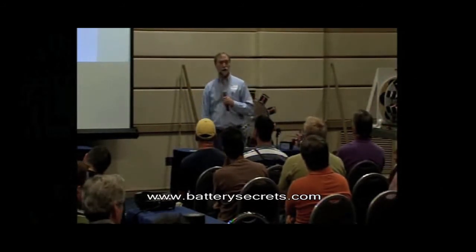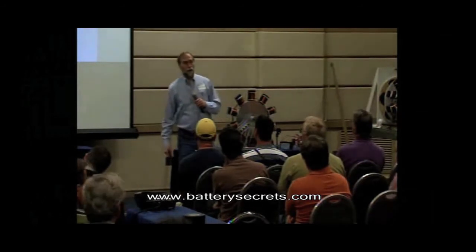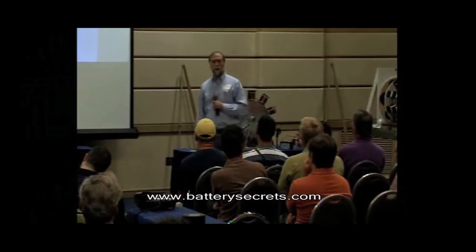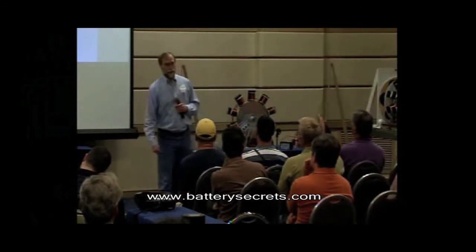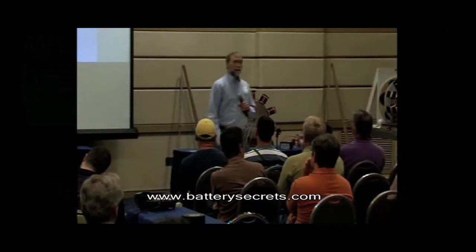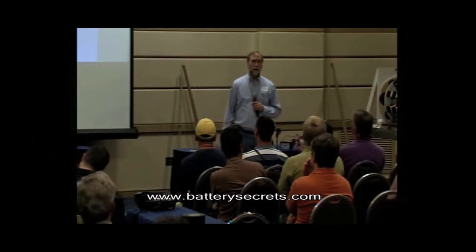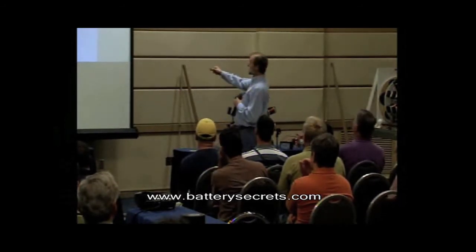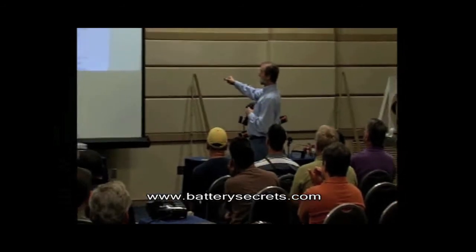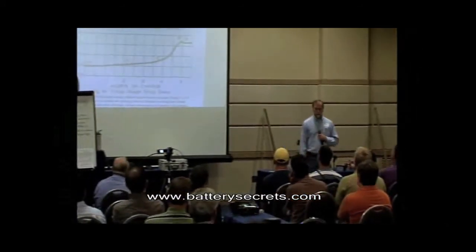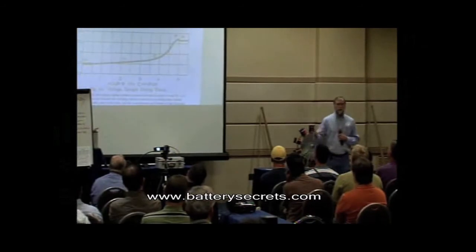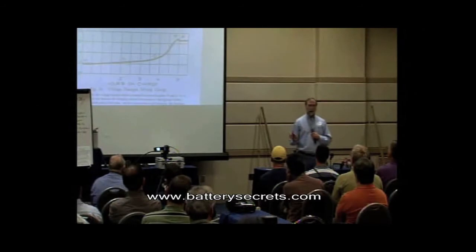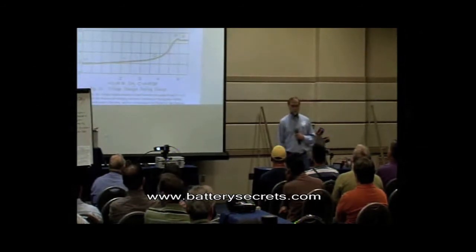So, is there a hypothesis about what this anomaly is caused by? John and I have no idea what it is. You're welcome to think one up. My bet is it'll be wrong. On the discharge side, did it discharge differently? Nope, the discharge was full. In other words, when this happens, this is a chemical indicator. The chemistry is done. It doesn't go there for fun. It only goes there when the sulfate is 100% out of the plates and into the electrolyte.